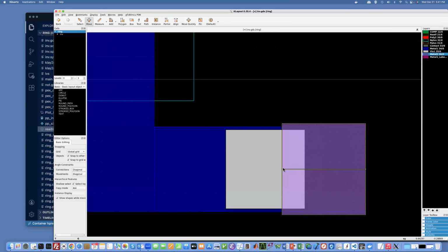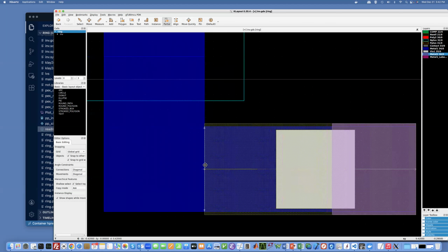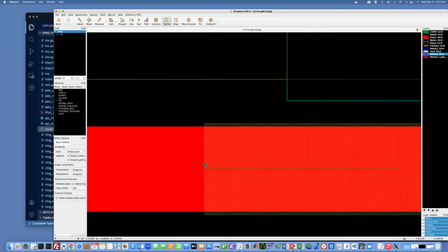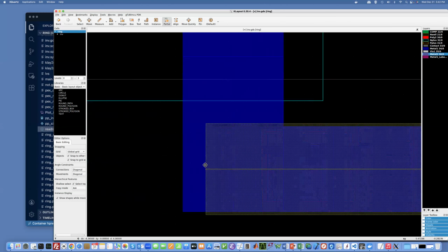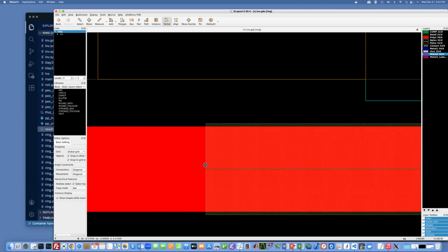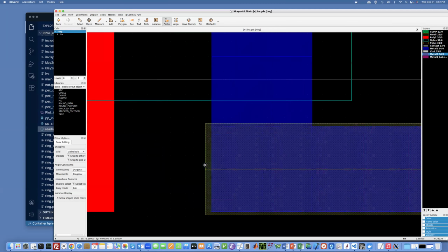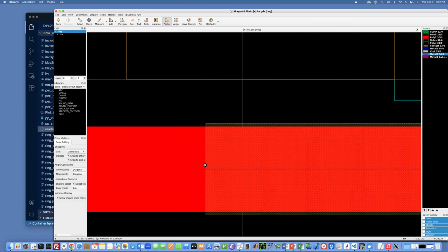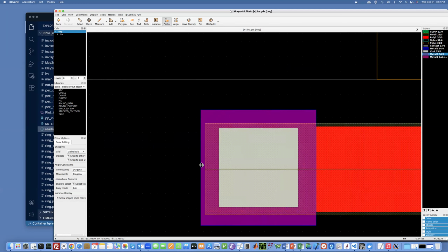So now it's nicely centered across the metal. Then at this point, last step is I'm gonna click on partial and stretch the metal layer all the way up to the via 1 corresponding to the input of the ring oscillator.